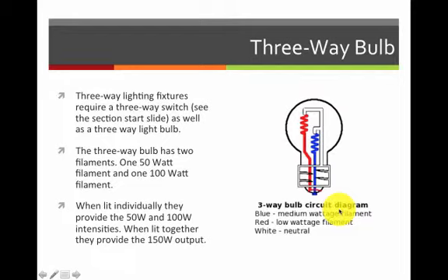Notice this diagram is very simple, but the real key is the bottom of the bulb. Most light bulbs have a single metal piece on the bottom, and then there's insulator. The bulb has this area where you have the screws that's metal, and that's usually where your neutral makes contact. That would be right here on the sides. But on the bottom of a three-way bulb, there's actually two metal contacts separated by insulators. And this is kind of the key behind the three-way bulb.